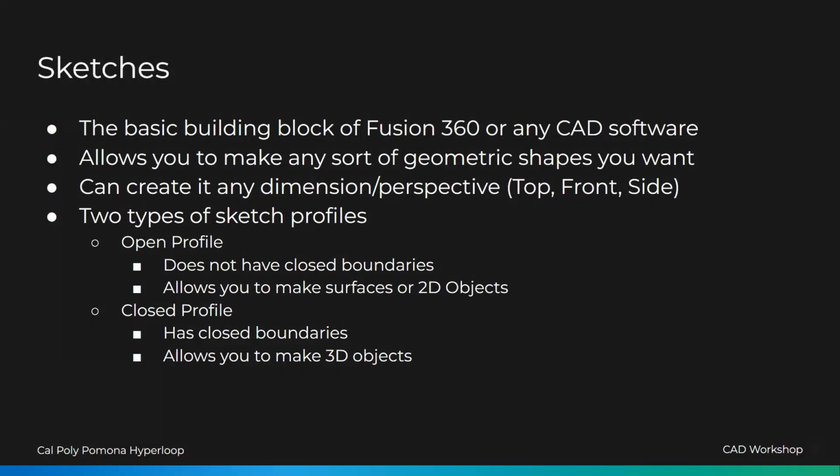All right. Sketches, you'll see this again when we get into it. But this is kind of where you start. A lot of times you'll create a sketch, and then that sketch will be revolved or extruded or cut, whatever. But you always start with a sketch and then you create 3D models based off of that sketch.